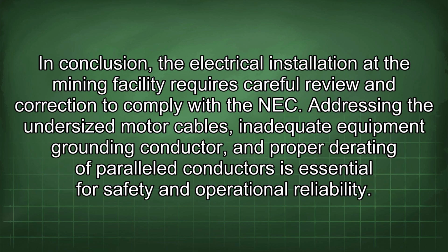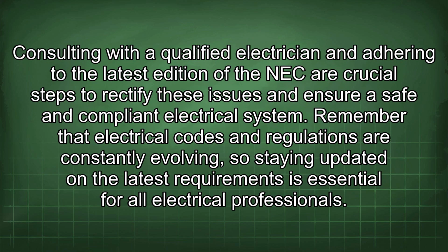In conclusion, the electrical installation at the mining facility requires careful review and correction to comply with the NEC. Addressing the undersized motor cables, inadequate equipment grounding conductor, and proper derating of paralleled conductors is essential for safety and operational reliability. Consulting with a qualified electrician and adhering to the latest edition of the NEC are crucial steps to rectify these issues and ensure a safe and compliant electrical system. Remember that electrical codes and regulations are constantly evolving, so staying updated on the latest requirements is essential for all electrical professionals.